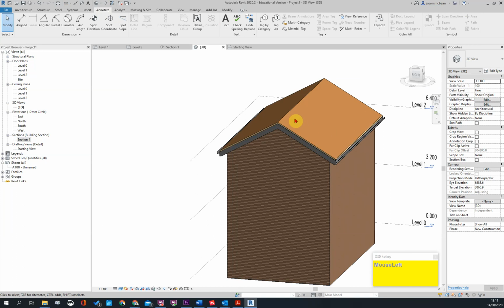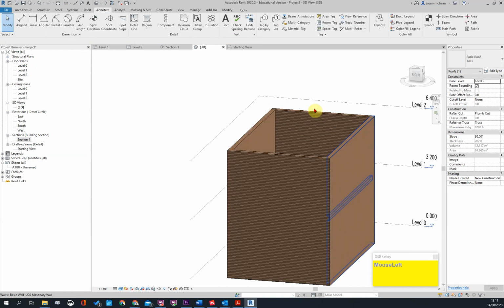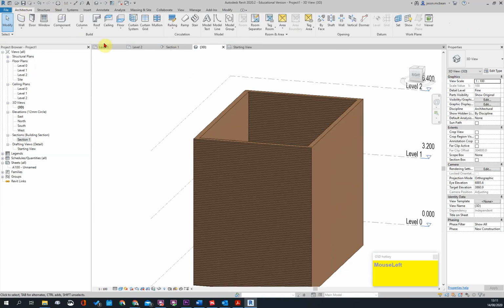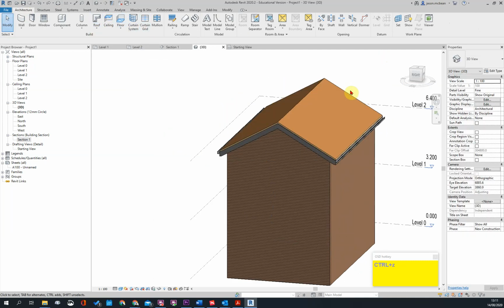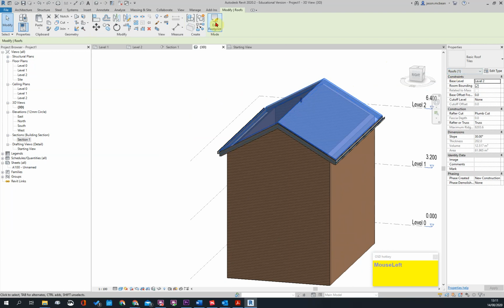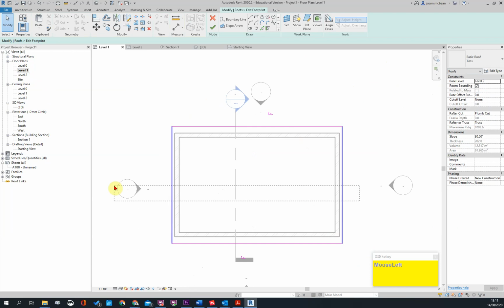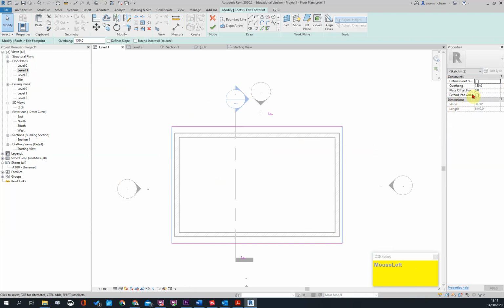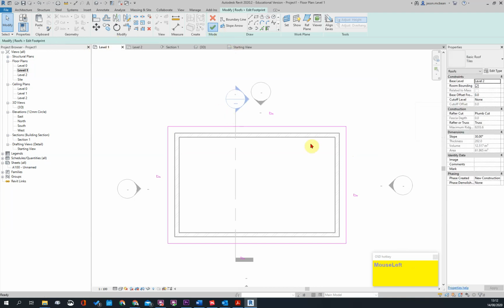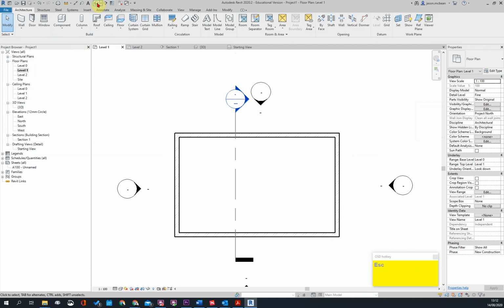So now there's another option to do a roof. Okay, so architecture. Okay, let me just go back. Say now, for example, I edit this roof plan because I want to have a pitch on either side. So if I go back here and I say, actually, this needs to be offset 350 as well, and the pitch needs to be defined slope. That also needs to be 30 degrees. Look, I'm going to show you what happens now if I go back to my view.